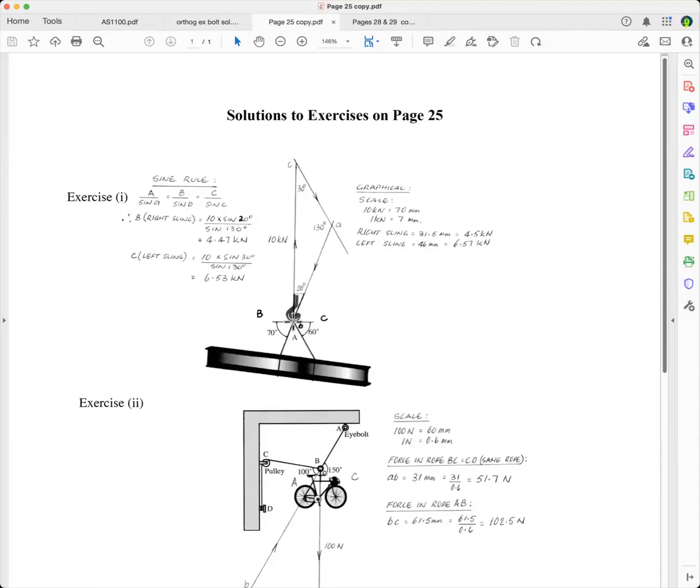There's the point. Everything's in equilibrium. It's not moving. So therefore, the force diagram will close up. And so you've got this 10 kilonewtons, which is about 1 ton, equivalent to 1 ton, is pulling up like that.